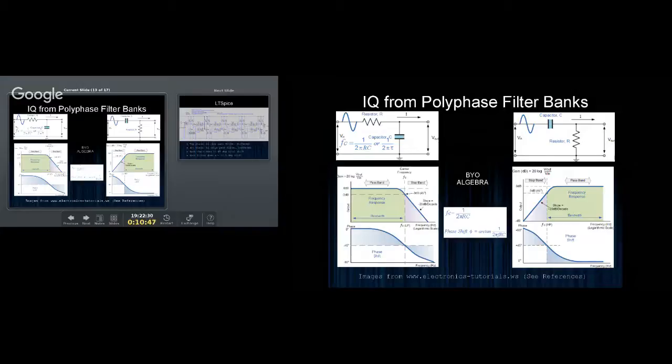The problem is that's also the -3 dB point, so you've got loss. What's arguably even more irritating is that you have a pretty strong roll-off regardless of where you sit, because you've got a high-pass filter and you've got a low-pass filter. So now if your frequency deviates either side of that center frequency or that corner frequency, you're going to have a pretty substantial amplitude modulation to go with your frequency modulation.